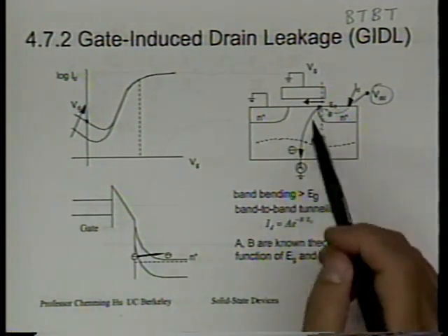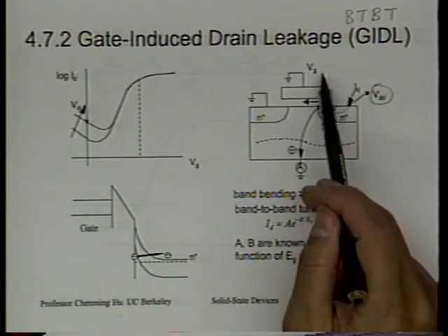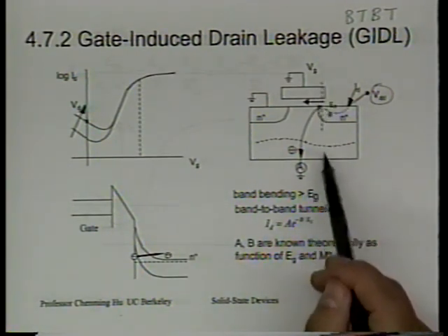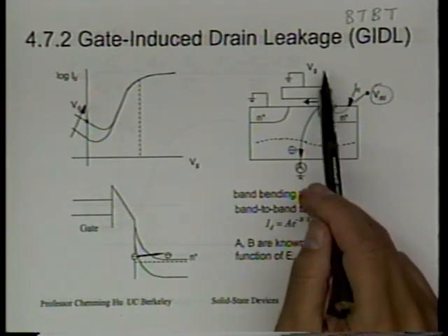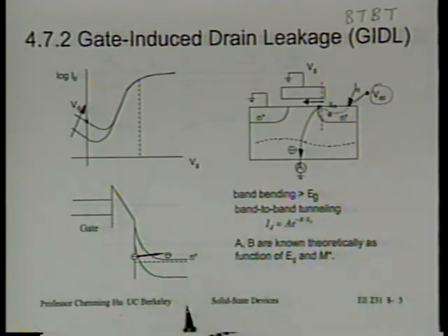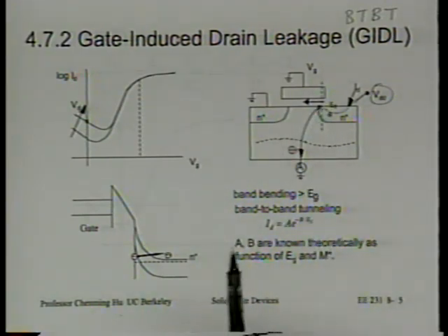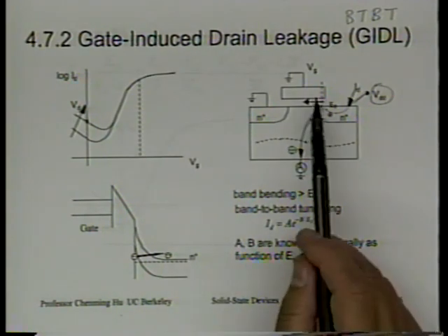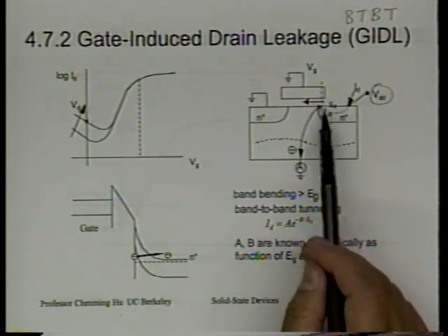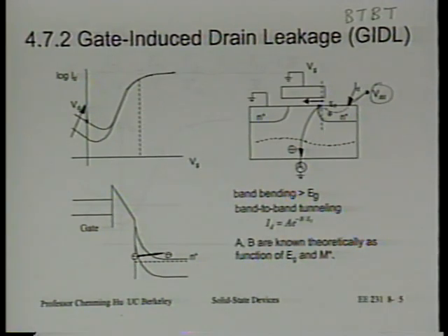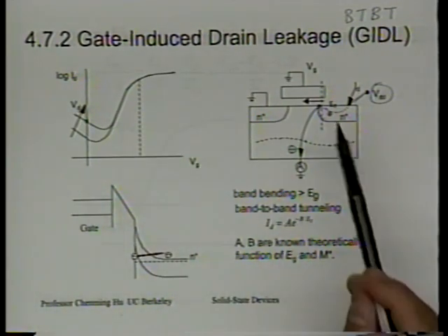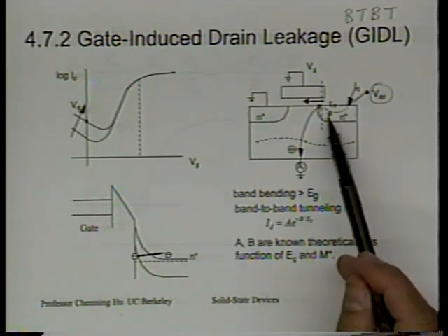Now, concentrate on this portion again, looking at this dotted line that I just drew. Okay, look at that dotted line. Along that line, can we draw the energy band diagram? Okay, this vertical line. Let's draw the energy band diagram. First, you will realize this is an MOS system, right? MOS capacitor. The substrate is N+ silicon. Now, is the gate more positive or more negative relative to the substrate?